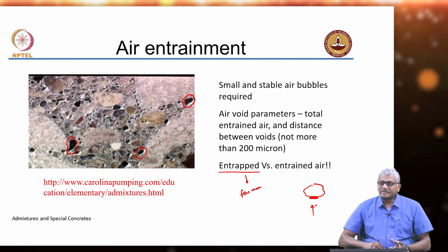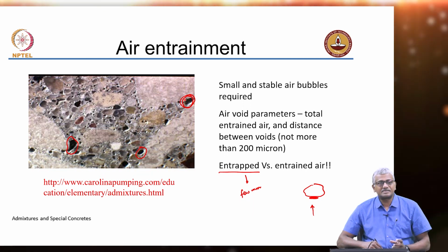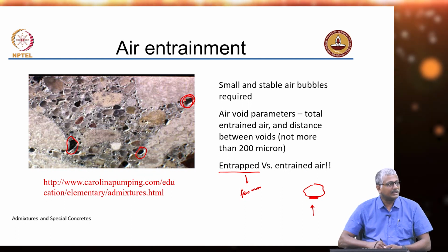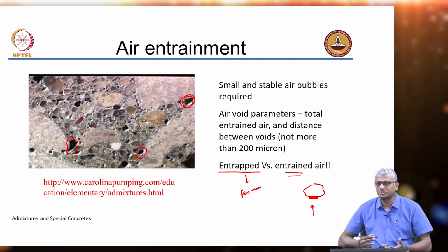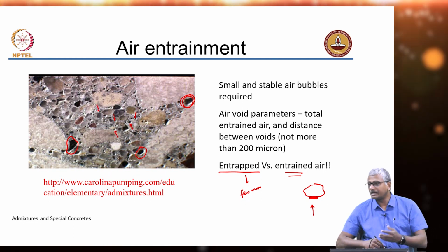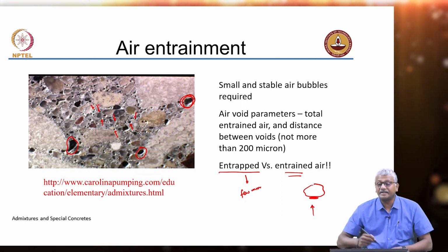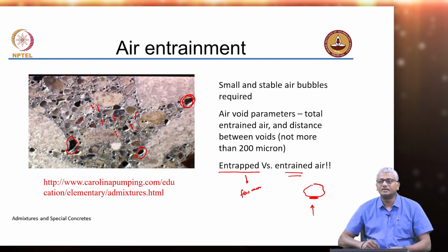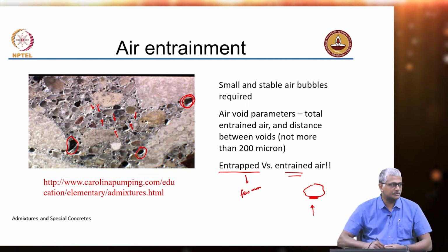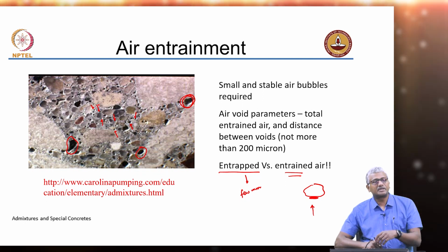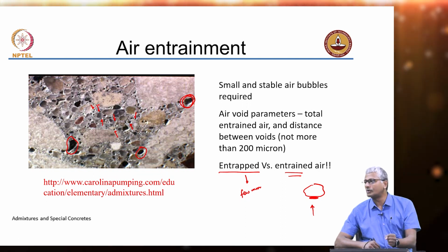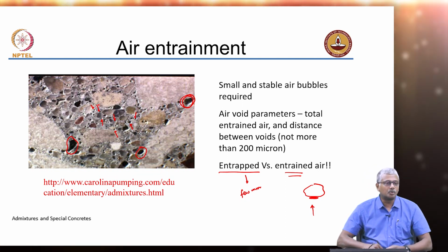This early strength development comes from the fact that C3S has a high reactivity because of its irregular structure. We saw a picture of cement clinker earlier, in which C3S had an irregular, polygonal structure, which leads to a high reactivity. And high reactivity also means it has a high heat of hydration. What do we mean by heat of hydration? It is the heat liberated when cement reacts with water. Cement is composed of different compounds, so the heat that is liberated depends on the heat liberation of individual compounds. The compounds that react faster liberate a lot more heat.